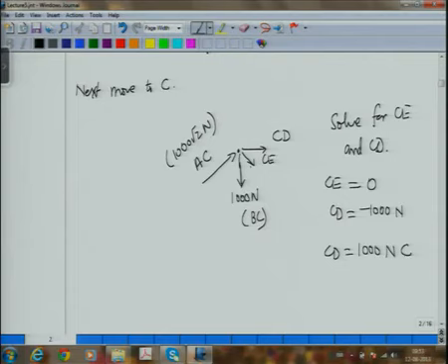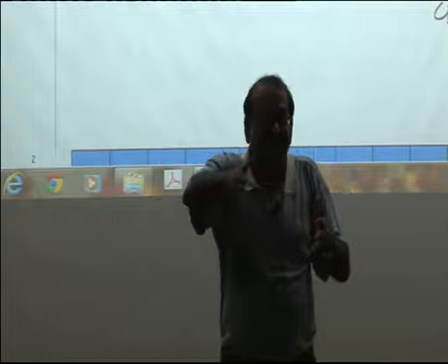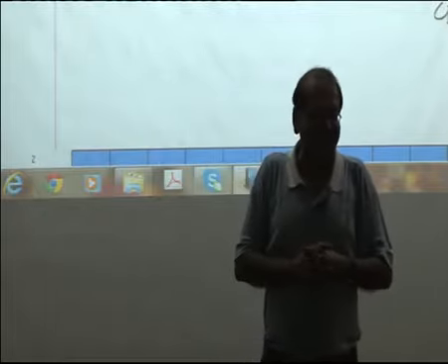And so on, and you can solve for the whole thing. Okay. So, this is called the method of joints, and as you would see, when we look at the method, we can term it as a brute force method for solving trusses. It is a brute force method, therefore, it is fit to be programmed because you make an algorithm, ask the computer to do things, because you do not have to use too much of your mind, it will keep on solving it joint by joint.